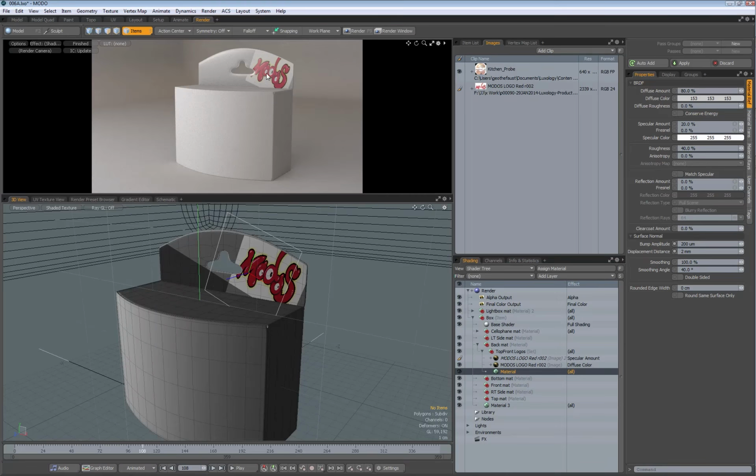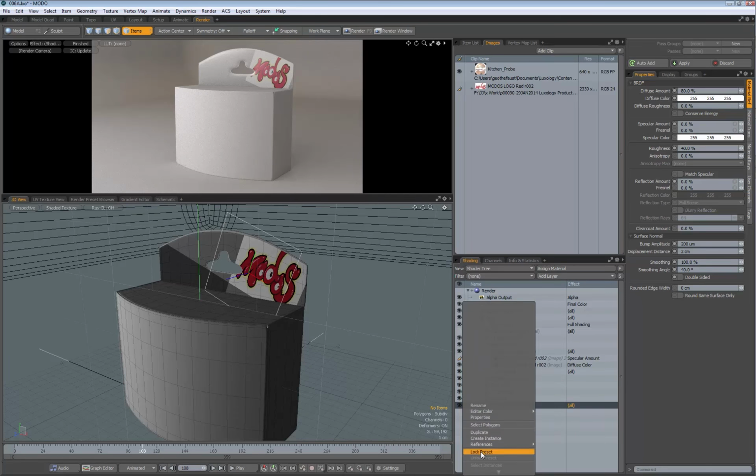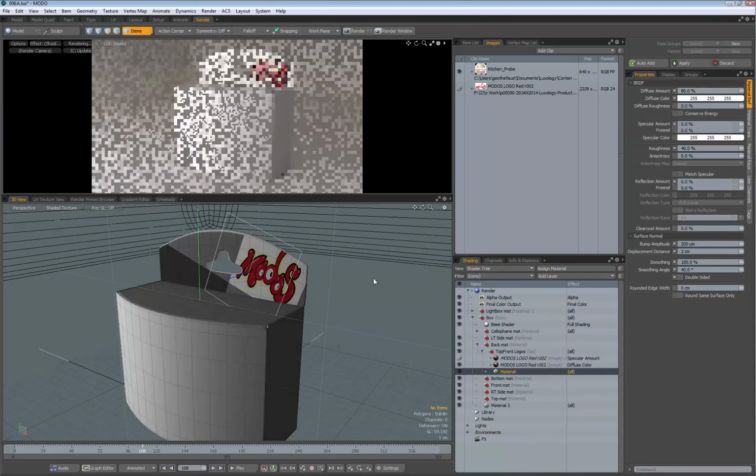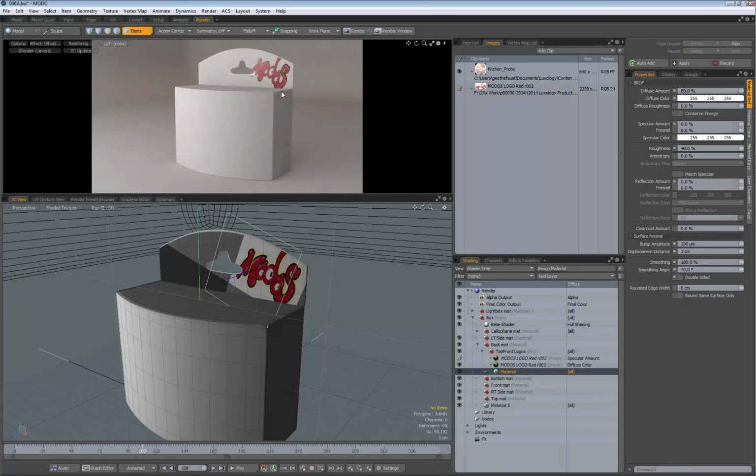And you'll notice that we had two different specular values in this area, and we have two different colors, which is definitely not wanted. The reason is because we have these two different layers on top of each other, and this one has some different settings from this one. What we can do is copy these settings here. Go down to copy, select the material we just created, right click and paste. And so now they match exactly.